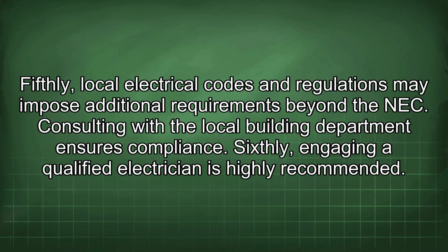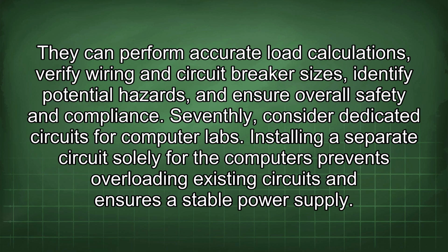Fifthly, local electrical codes and regulations may impose additional requirements beyond the NEC. Consulting with the local building department ensures compliance. Sixthly, engaging a qualified electrician is highly recommended. They can perform accurate load calculations, verify wiring and circuit breaker sizes, identify potential hazards, and ensure overall safety and compliance. Seventhly, consider dedicated circuits for computer labs. Installing a separate circuit solely for the computers prevents overloading existing circuits and ensures a stable power supply.